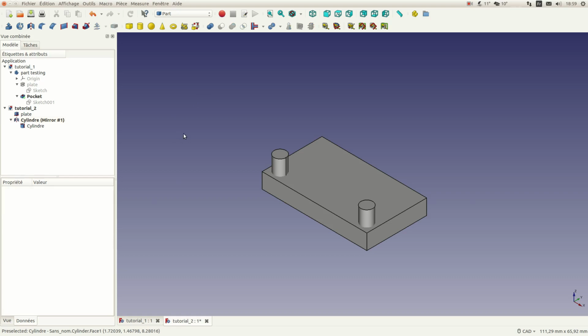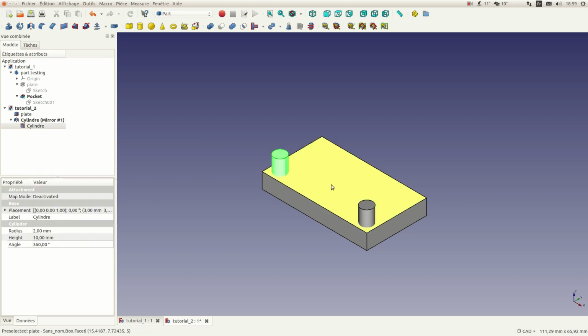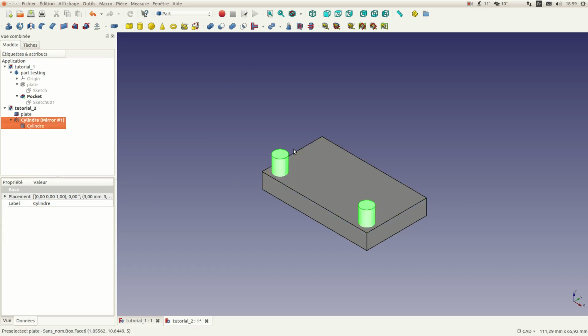and it helped me to create the second cylinder in the proper position. So now I can do the same thing to create a mirror, but if I want to make it in an easier way, I can use some special function. So this workbench is able to manipulate the things with adding, subtracting, and so on. So if I choose the first cylinder and I click on Control and use the second cylinder, I select the 2 cylinders, and if I ask the system here to make a union of both cylinders, I click on it.